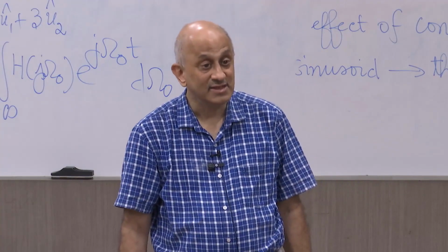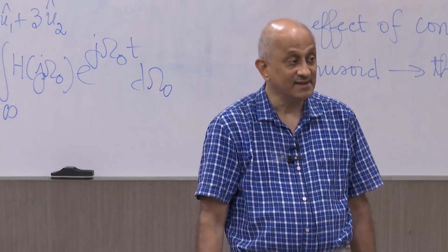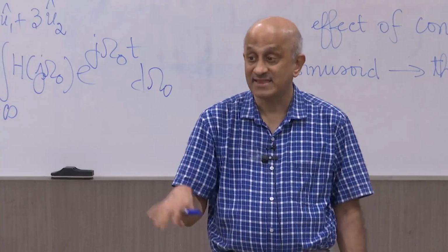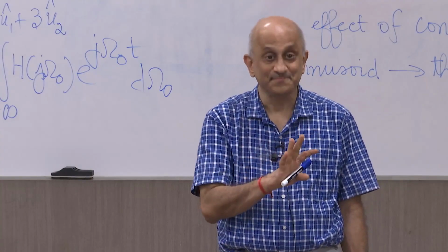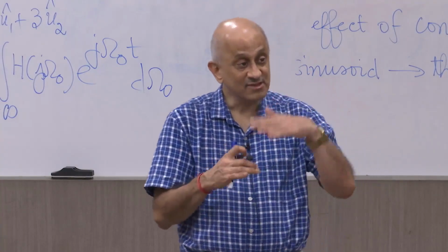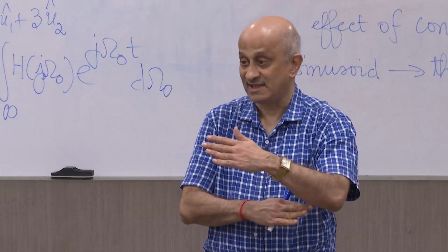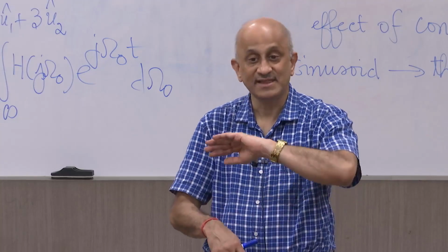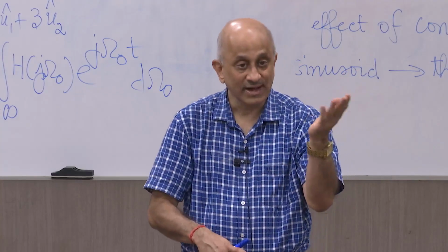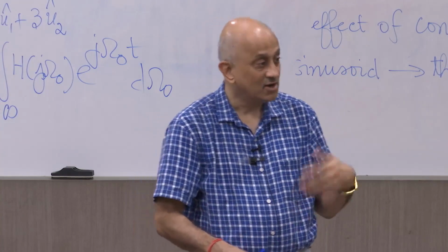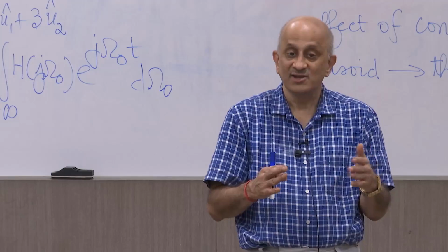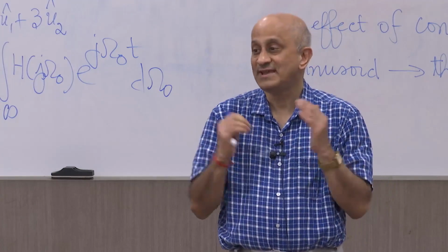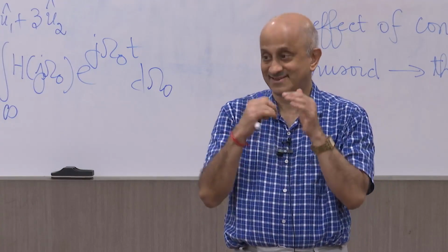So whose angular frequency are we looking at? It's the angular frequency of the phasor. What is a phasor? A phasor is a rotating complex number. The phasor is not really the same thing as a sinusoid. In fact, a sinusoid has two phasors embedded, right? One phasor rotates counterclockwise and one phasor rotates clockwise. So any sinusoid actually has two equal and opposite frequencies creating it.